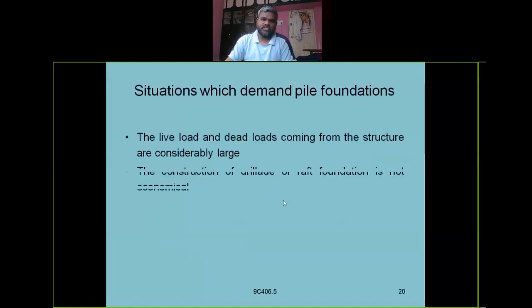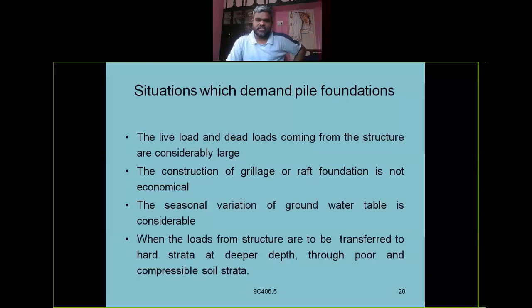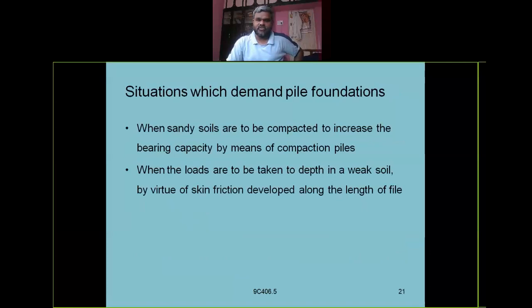Situations which demand pile foundations: when the live load and dead load coming on the structure are considerably large; when the construction of grillage or raft foundation is not economical; when the seasonal variation of the groundwater table is considerable; when the loads from the structure are to be transferred to hard strata at a deeper depth through poor or compressible soil strata; when sandy soils are to be compacted to increase the bearing capacity by means of compaction piles;